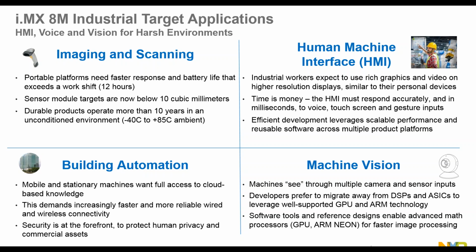When we go to industrial types of applications, we see applications getting portable with faster response, battery life really going down. And here's a key point of differentiation with embedded applications. Usually you require 10 years of lifetime for your products, a guarantee of supply, and a broader temperature range of operation. The same you don't find in typical consumer applications like cell phones. Usually the lifetime is about 2-3 years for a phone at most. So when you are designing a user interface or embedded designs, you need to consider solutions that can provide the supply lifetime that you have.